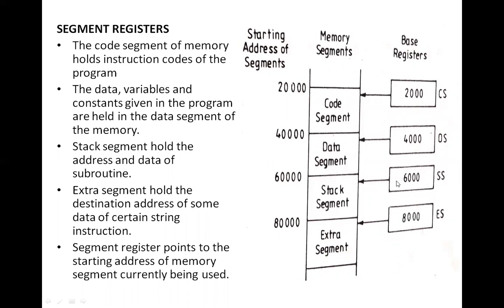So that we will discuss later on, what are the different addressing modes and how the effective addresses are taken depending upon the addressing modes. Now, as far as the stack instructions such as push instruction, pop instruction, call instruction, and return instruction are concerned, the content of the stack pointer and the content of the stack segment register are used to compute the address of the stack location.